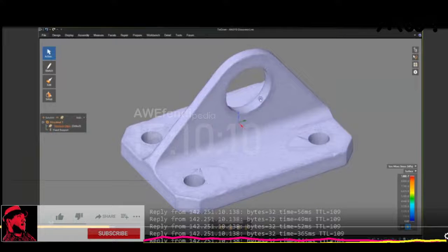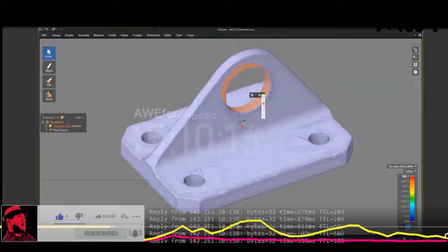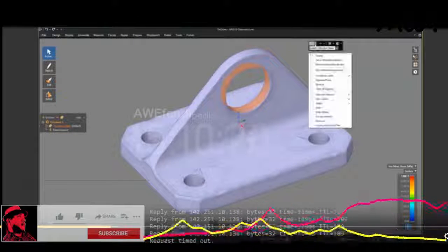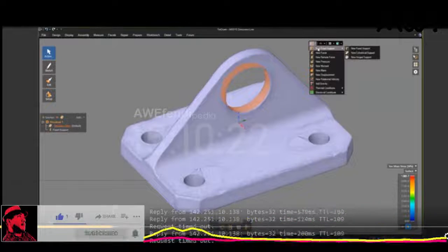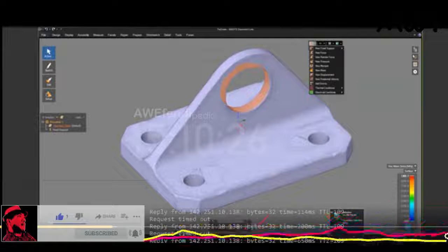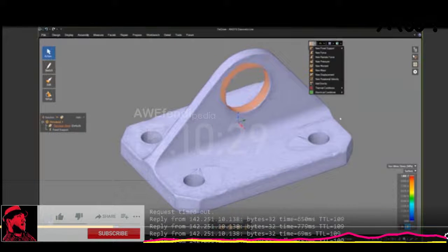The next thing I want to do is come in and select all of these facets here that represent this hole here. And my goal is to apply a force. Now, look how easy it was just to select, what does it say down here? 11,706 facets, and then apply a boundary condition to it.